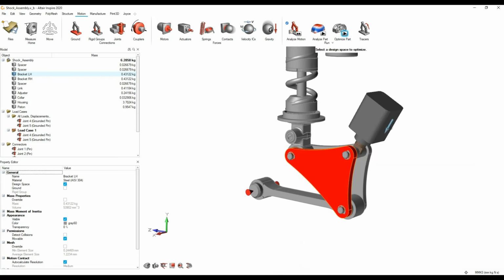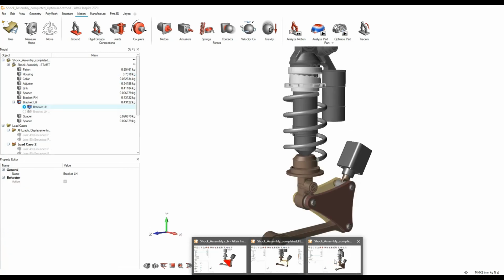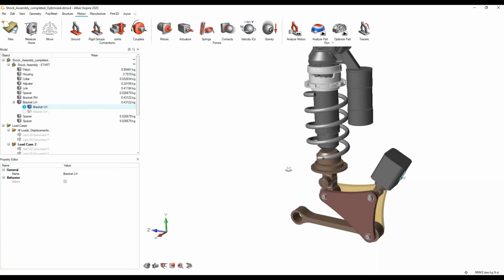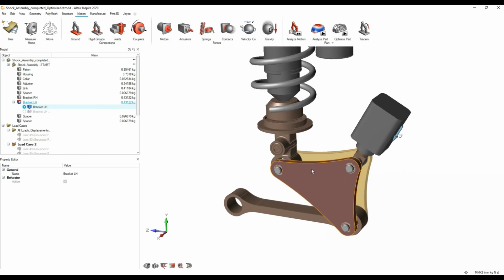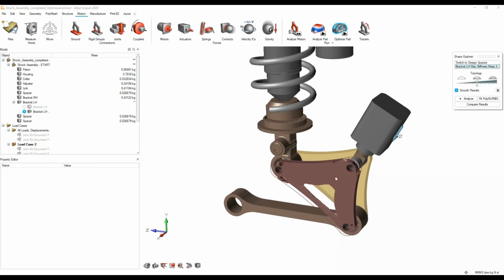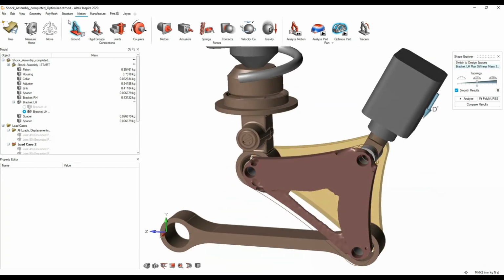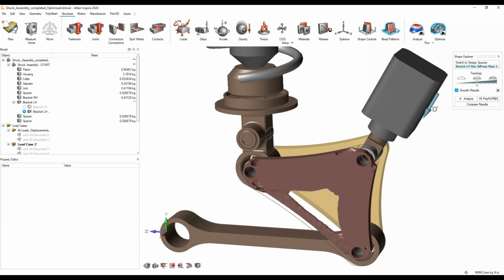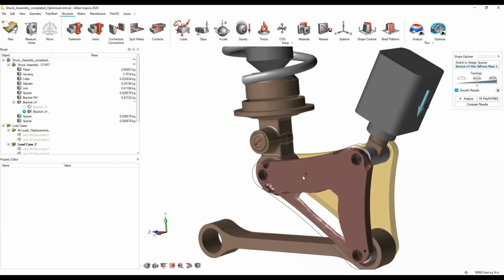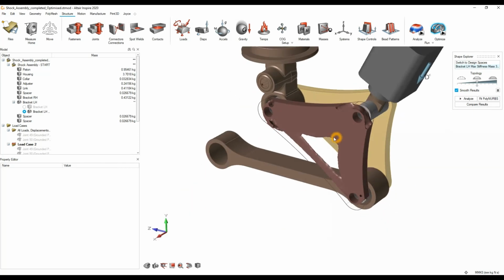Now I already have one that ran, as it only takes around 20 minutes to run. So you can see it's the same setup again, and once it's finished running, just by clicking on the truss button at the top here, you can see that this now gives you a new design. If you head back into structure, you can specify other manufacturing constraints as well, if you want to specify symmetry or draw direction, etc. But the Inspire structural analysis video should take you through that instead.